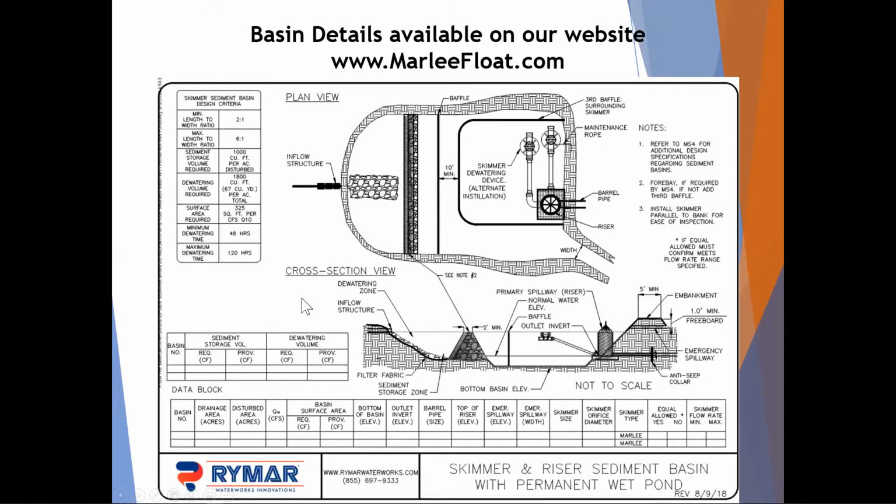And again, our basin detail, this is the permanent riser configuration detail for one with a permanent pool. Sediment basin criteria is pretty similar. We've added a sediment storage volume required in the chart. We've added some tabs here for the sediment storage volume required and provided.